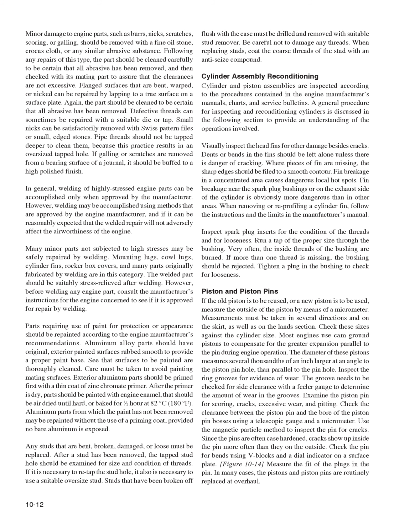Since the pins are often case hardened, cracks show up inside the pin more often than on the outside. Check the pin for bends using V-blocks and a dial indicator on a surface plate. Figure 10.14, measure the fit of the plugs in the pin. In many cases, the pistons and piston pins are routinely replaced at overhaul.